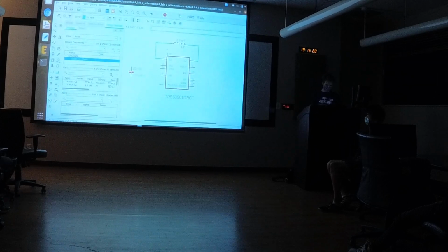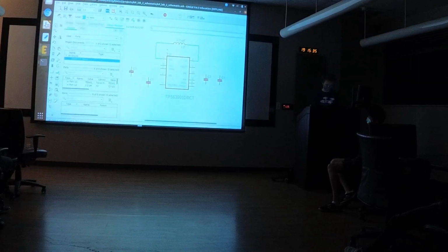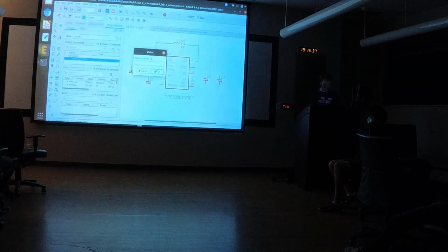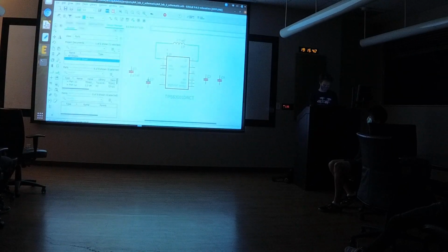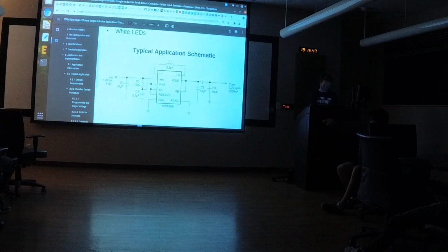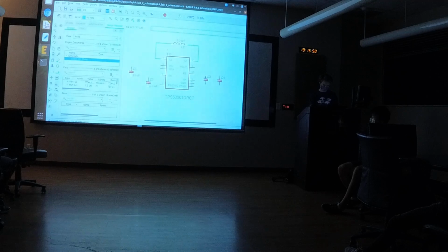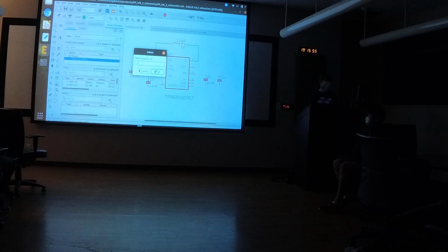If you remember, we had 4 of them, so 1, 2, 3. And what Alexa's doing here is really smart. Just make sure you read how many you need and just boom, boom, boom, boom, so you don't have to keep reopening and closing. Right, and then looking at this, it's 10 microfarads. What we're going to do is find this little cross here, which is hidden, click it, type in 10 microfarads. We're going to look at this one, 0.1 microfarads, and again click this block, blah, blah, blah. This is very smart as well. Just value all of them before you start wiring them up, so that after all your components are on, you start wiring, and it makes it a lot easier, or at least it saves time.